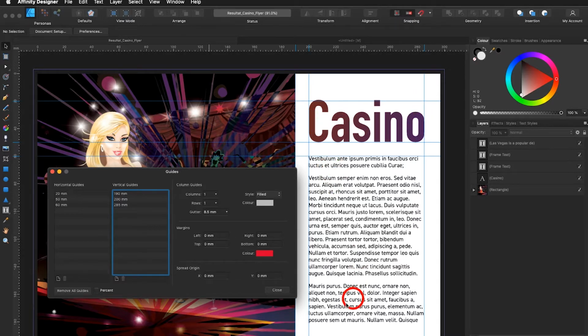Now let's say I would like to add one here below. I can go under horizontal guidelines and kind of guess where it's going to be placed, add horizontal guideline. You see it just placed one at 105. It's too far up. I would like to place it down here, so I have to guess. Let's say I place it at 200. I hit the enter button and you can see the guideline is down here. Of course, you can adjust it and kind of guess back and forth until you have it.